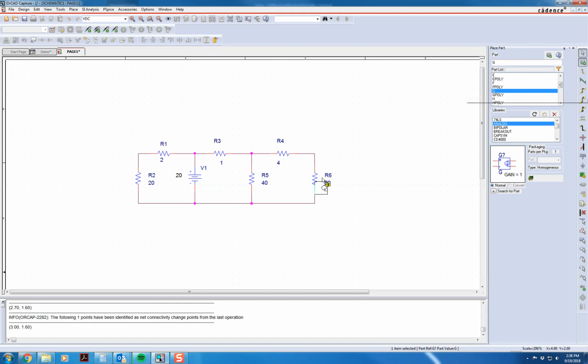and I'm going to go ahead and mirror this horizontally. Now you have to make sure, and it does say that my current is going down, and so you can just drag this wherever you want to. You want to keep it pretty close to the component, but this is the current that's going down. Now this is a little messy, or it can be. So this isn't too messy yet, so it just goes in right here like this. And then the voltage, well, the positive side of the voltage is over here. So I'm going to bring it down. So that's the positive side of the voltage.